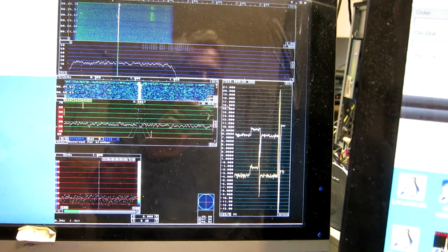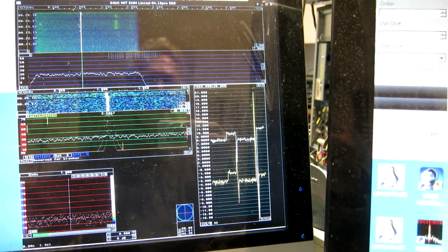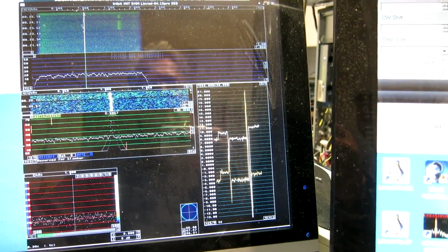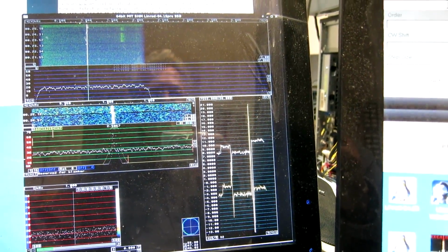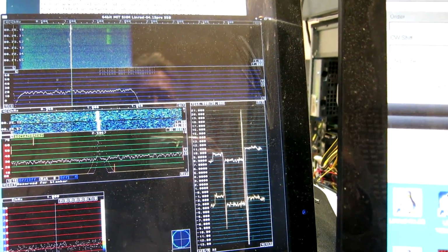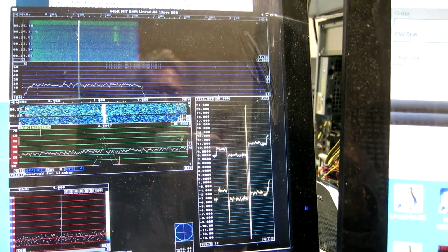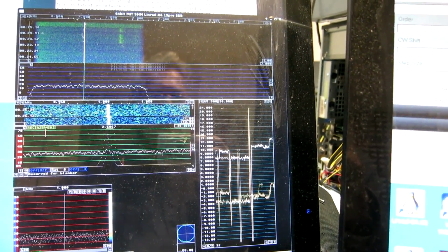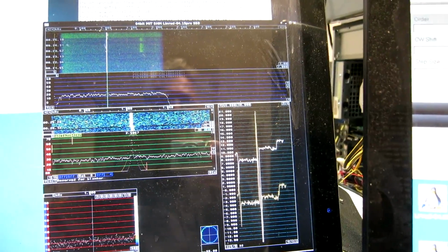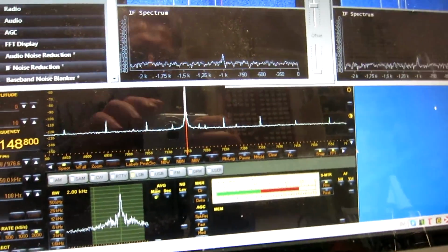And signal to noise ratio seems a little bit better. So I increase 1 dB. And then I remove this strong. And there's a little bit more than 3 dB loss, so I shouldn't have added that 1 dB. Which means I have the same, -22 dBm.